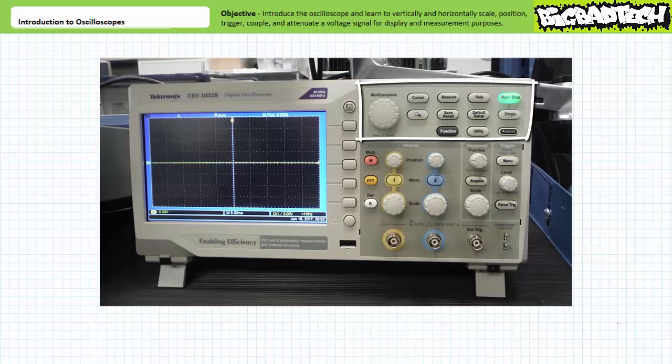The fourth group at the top is all the buttons one uses to measure, set up, save, recall, or otherwise operate the oscilloscope. Within this group, the multi-purpose knob in the upper left is the principal means one uses to select menu options displayed on the screen. It's somewhat tricky to use in that an operator rotates the knob to navigate within a menu and then pushes the same knob to select the option. We'll examine menu navigation in a moment.